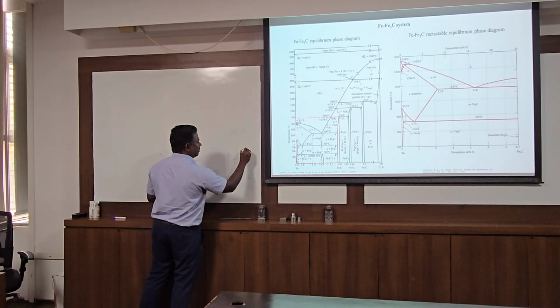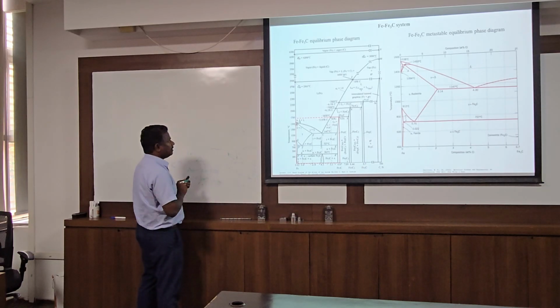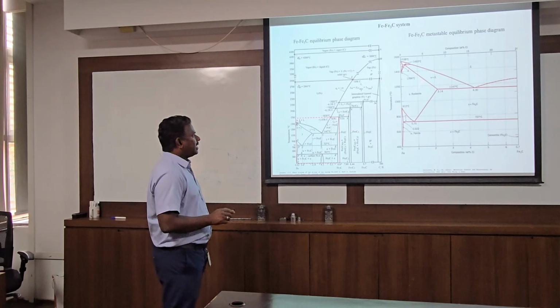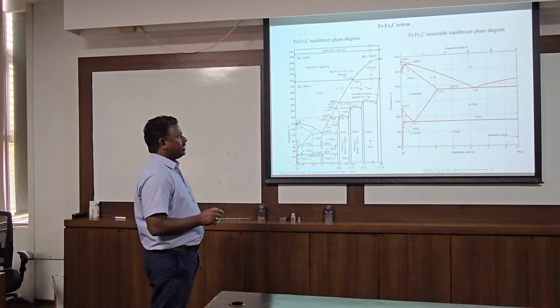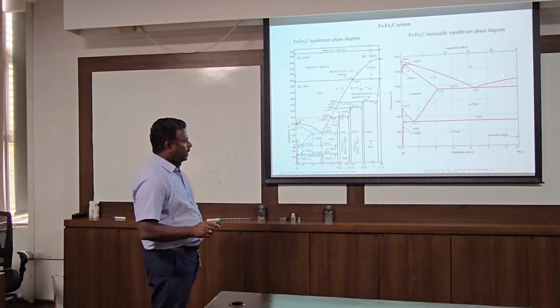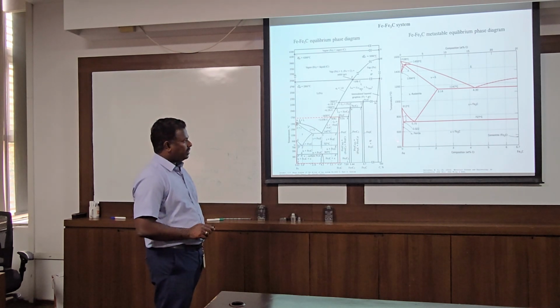Solid plus liquid gives one solid. This peritectic reaction happens at high temperature. It is also not very important for engineering applications. Yes, it has some negative impact on cooling and so on, but we don't much deal with it. For cast irons, we deal with the eutectic, and for the general steels we use regularly, this is the reaction we go through. This is the eutectoid.